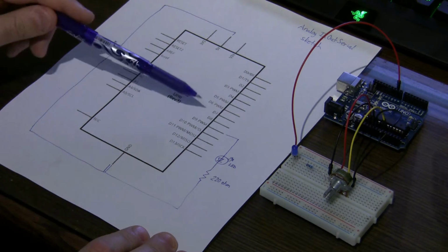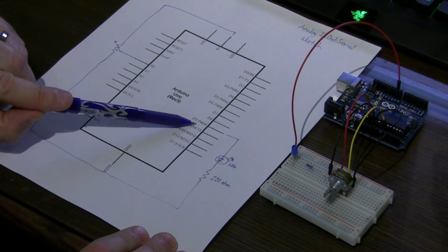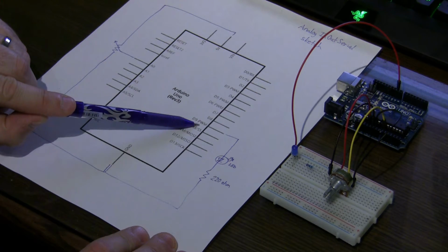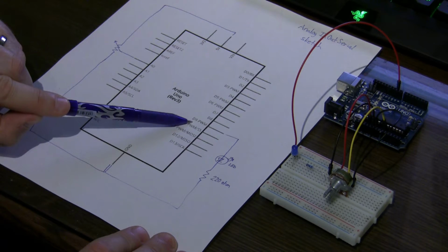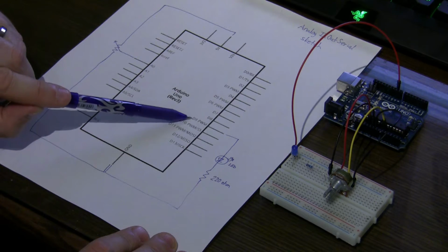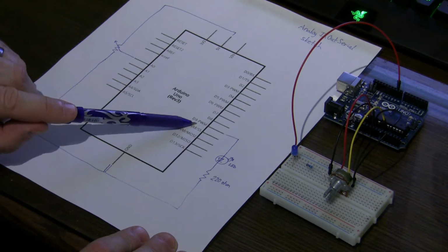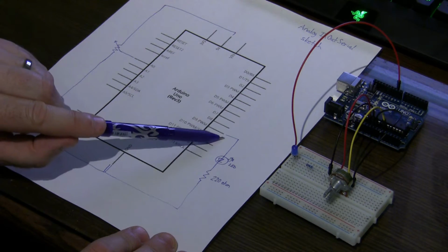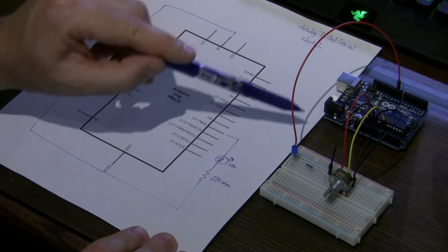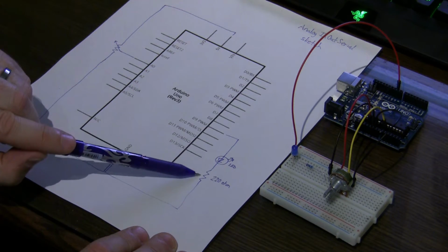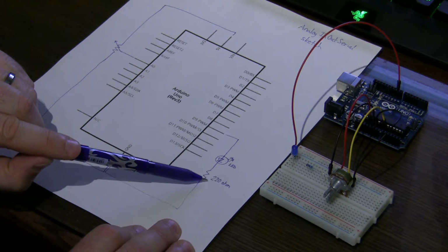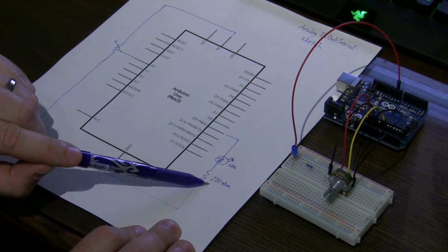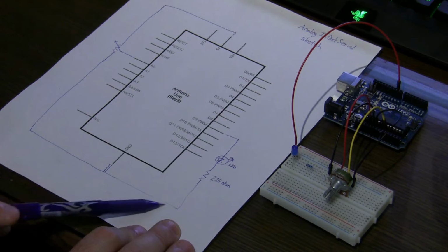Now on the other side, we're going to use one of the pulse wave modulation pins. We're going to use D9 like we did last time. Which one was that? I don't even remember what the name of that sketch was, but we're going to use pin 9 for PWM as the power source. That one goes to the LED. In that circuit, we're going to have a 120 ohm or greater resistor, and like I said, I'm using a 220 because I don't have a 120 in my kit. And then that one goes to ground.